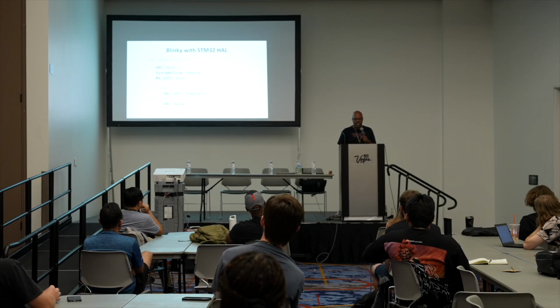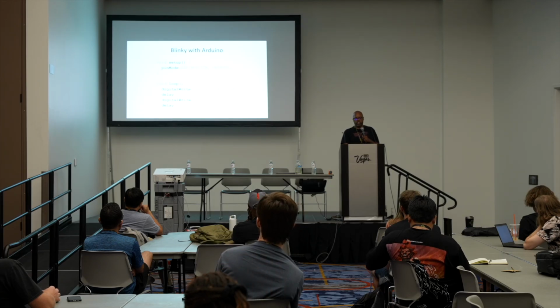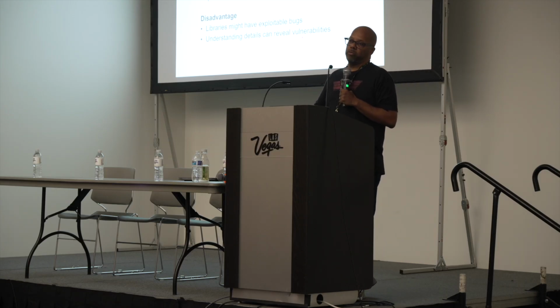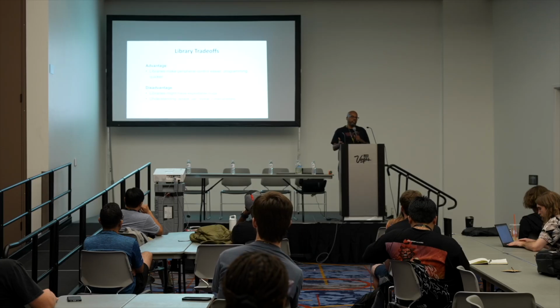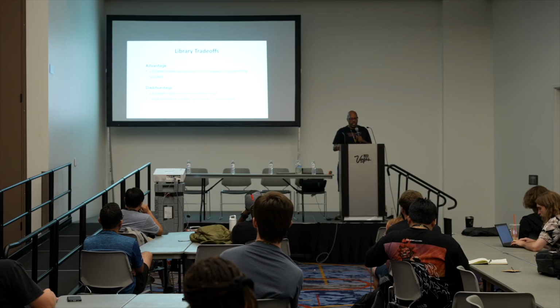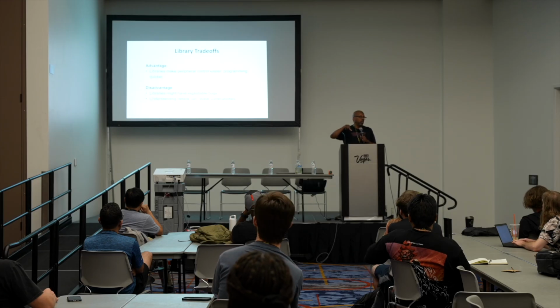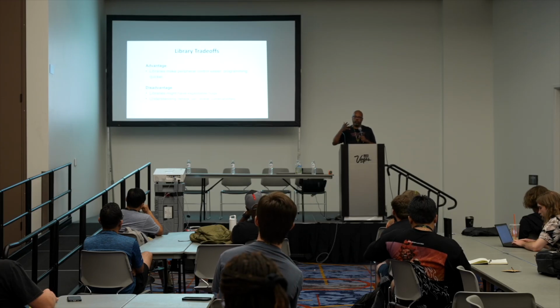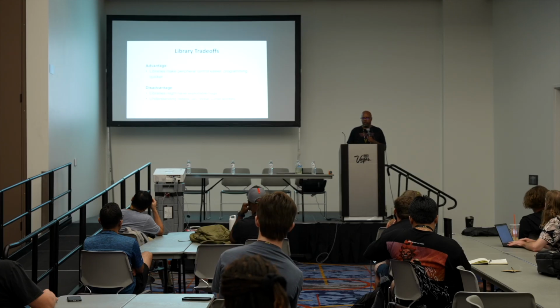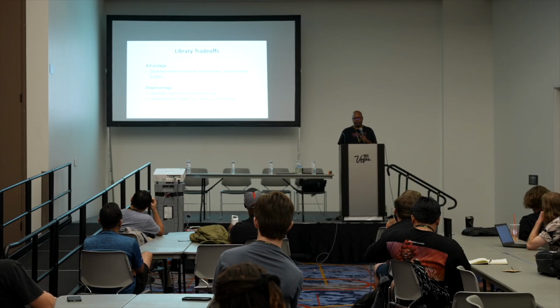So anyway, that's HAL. And then with Arduino, here's how you might write it. Either setup or loop, and digitalWrite is their function. Now, you know, trade-offs with the libraries: the advantage is it makes everything easier. The disadvantage is that the libraries themselves might have exploitable bugs, okay? That's one security difficulty. But also, they're generally slower, right? So it depends on how efficient you really need to be. Most of the time, people use these libraries, though, in all honesty, because they do make things more convenient.